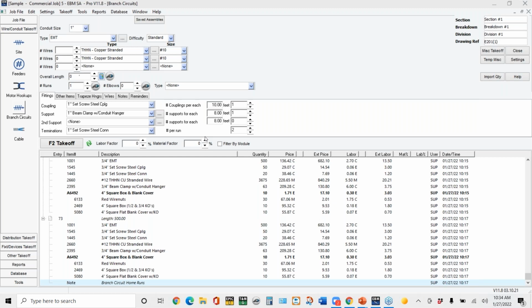There was one, Mark asks, this looks great, but I'm trying to figure out how to include 2 dimming wires for 0 to 10 volt lighting systems. Okay, so that's pretty straightforward. Again, if you're using this for your lighting portion of the job, instead of using MC cable, you would use luminary cable, because the luminary cable has the 2 extra wires for dimming.